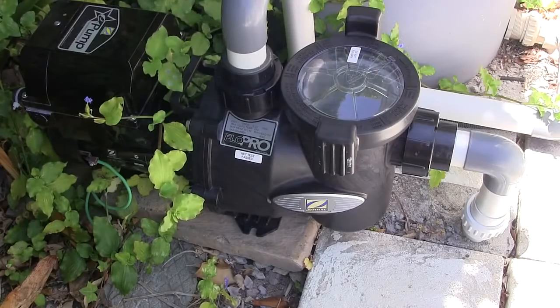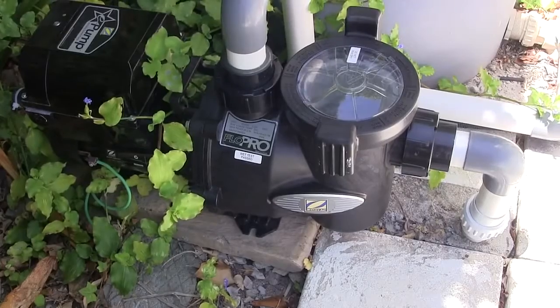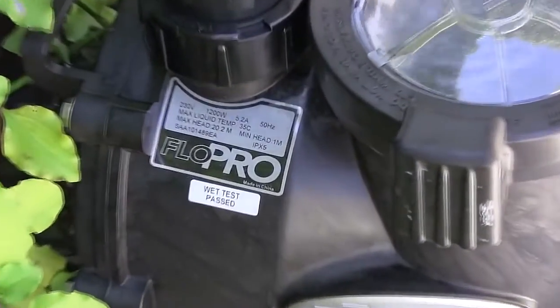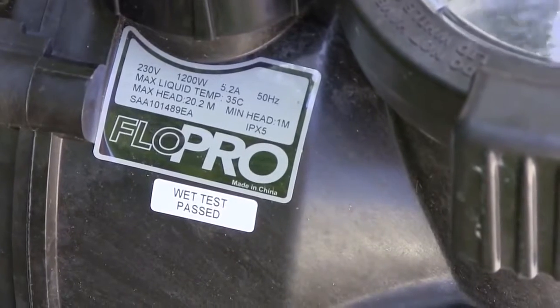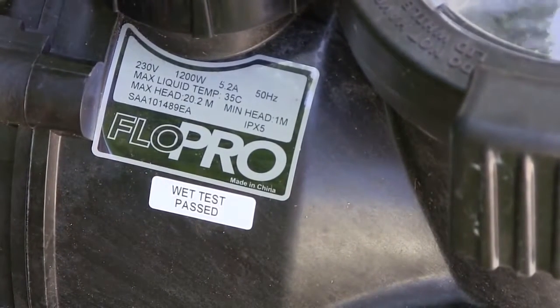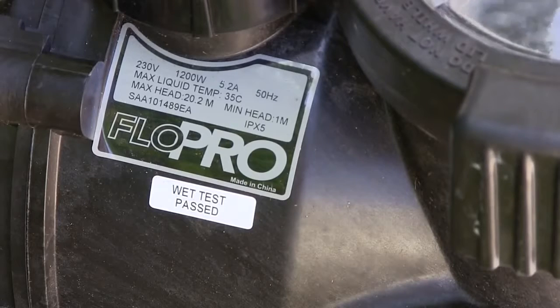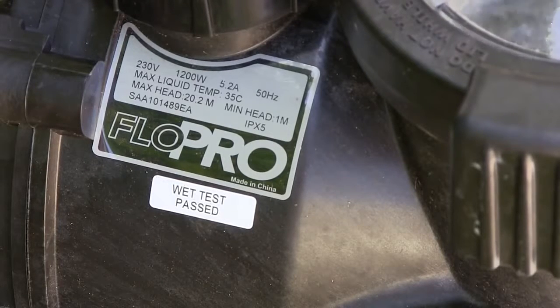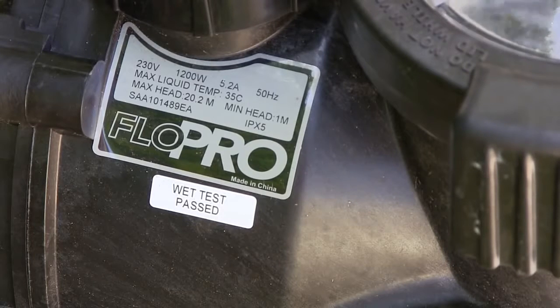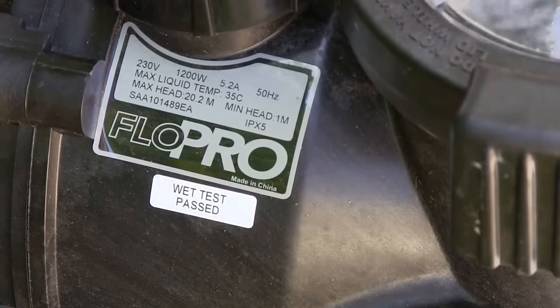And that I obviously specify on a clock with the controller for it, which I'll show you now. But what I wanted to highlight is you can see on the actual plate over there with these specifications that it is rated for 1200 watts. But this will comfortably run the pool cleaner at 250 watts now in its slow mode. So I kick it down to the slow mode for the latter part of the afternoon when I potentially know the solar power is going to start waning. But in the peak of the day, I have it running at higher RPM for better cleaning and better filtration.